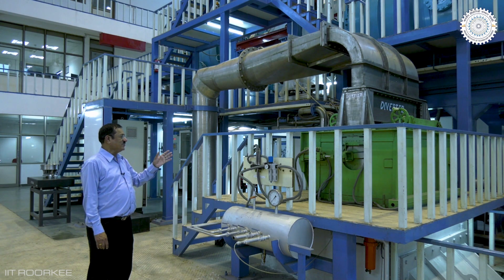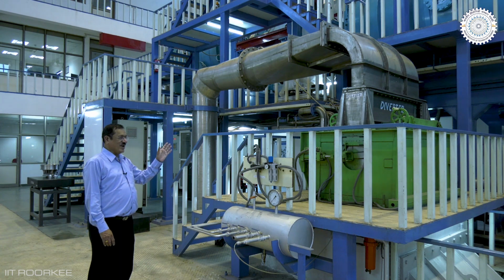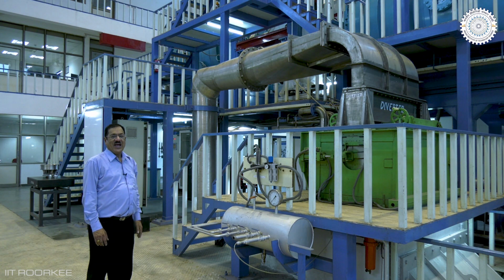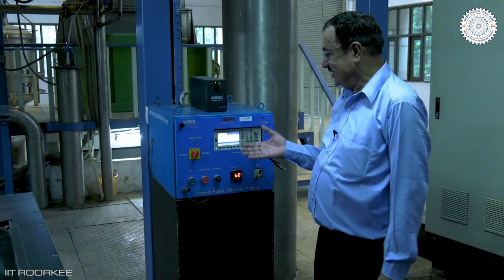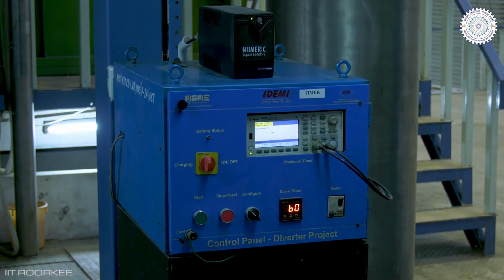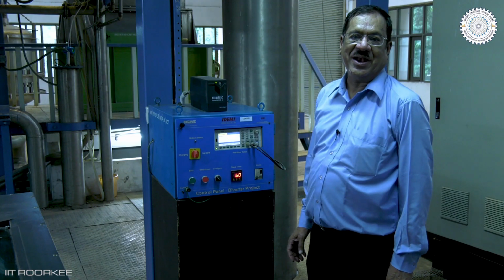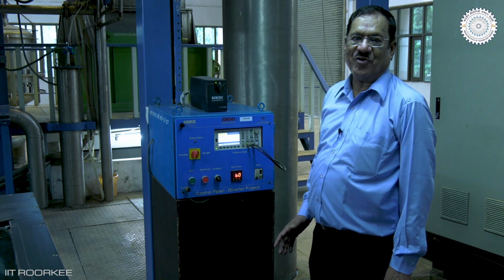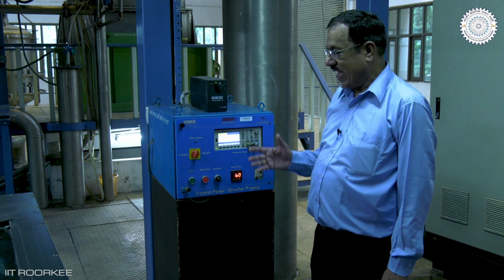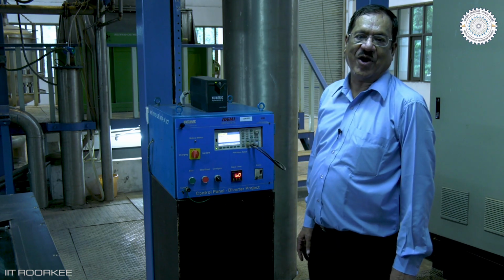Normally the water keeps on flowing back to the reservoir, but when we want to calibrate, this flow diverter will divert the water to the main measuring tank and we know the weight of water collected. When this is done, the clock is also automatically put on and off. We know the time of diversion, thus we know the actual flow calibration rate. This is a precision 8-digit timer which is used during flow calibration and we get a very accurate time. This is put on by one sensor and put off by another sensor. So we know the exact time of diversion which is required for flow calibration.